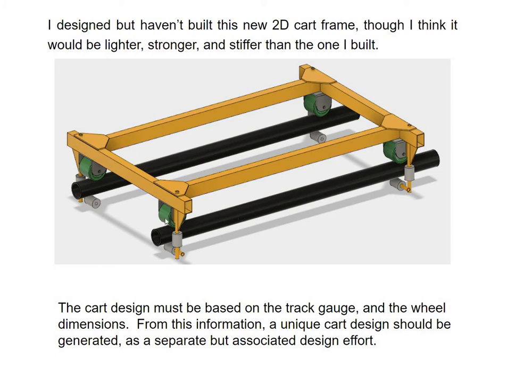Then you get all these pieces, design it. I do have this design I could give somebody. You can see there are steel sleeves welded into this assembly. These are long steel sleeves, and almost all of the fasteners you use are going to be grade 8 5/16 fasteners. You can see where you weld these things together, and there you have your main wheels, your side wheels, and the upstop wheels.